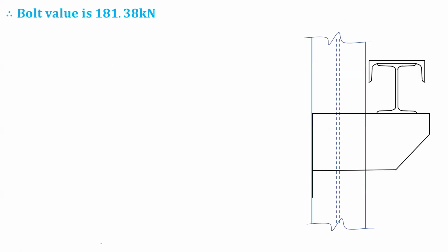So now I will use 6 bolts, 6 on this face, 6 on the opposite face, so we have a total of 12. Now if we go to the CG of the bolt group in this, we have the center horizontally in this fashion, and vertically like this. So now we have these 4 bolts, 1 2 3 4, which are at equal distance. And what is the value of R? Let us say this will be R1. So how will we find this value of R1?